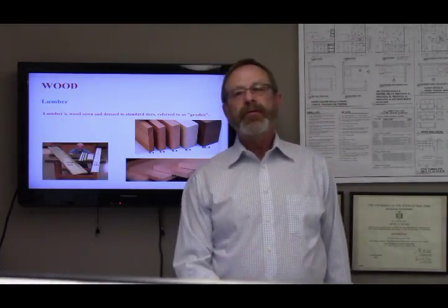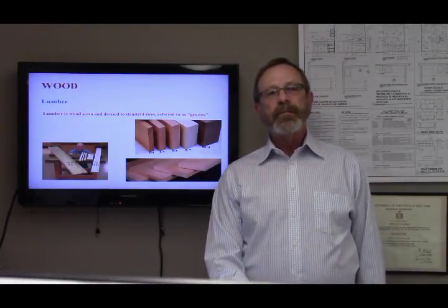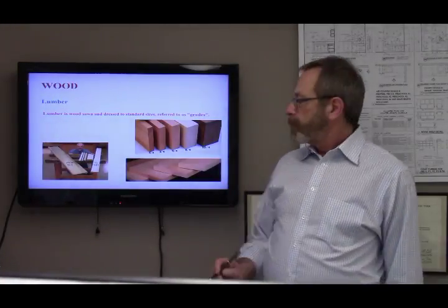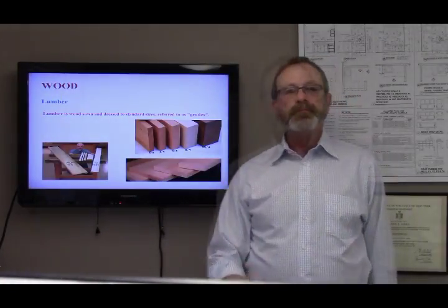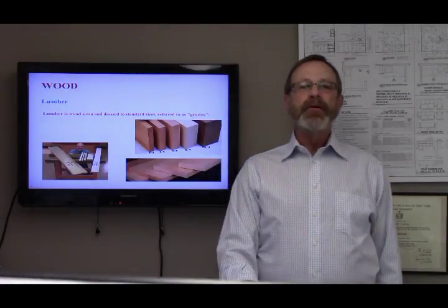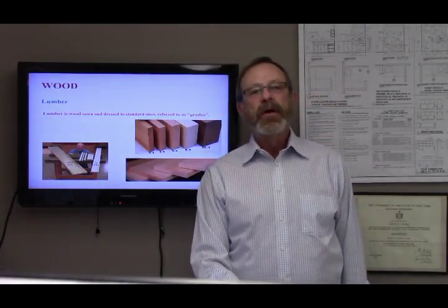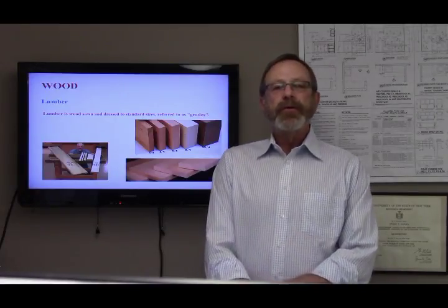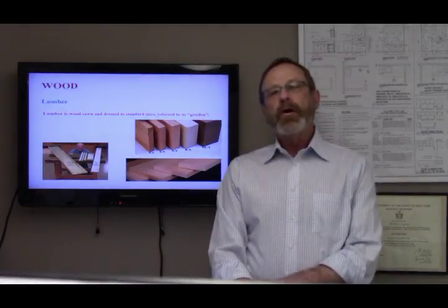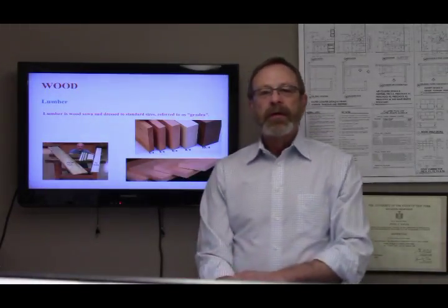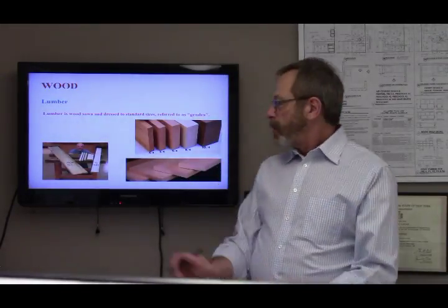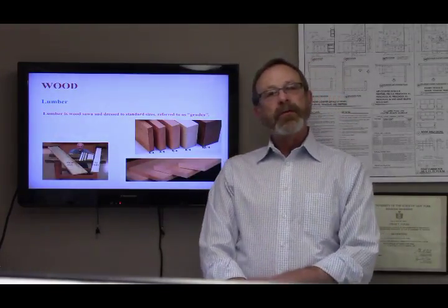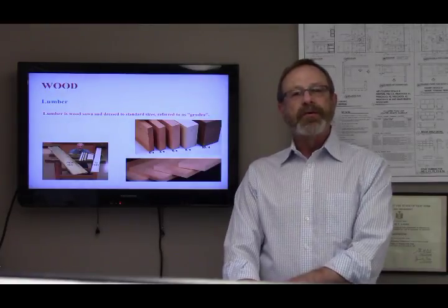We are used to standard sizes like 1x6s, 1x12s, 2x8s, but in this slide you'll notice some fractional widths as well. In short, these fractions refer to the thickness of the hardwood lumber. The thickness is expressed as a fraction and goes in increments of quarters of an inch. So a 4/4 is equal to 1 inch. A 5/4 is equal to 1 1/4 inch. A 6/4 is equal to 1 1/2 inches, and so on.